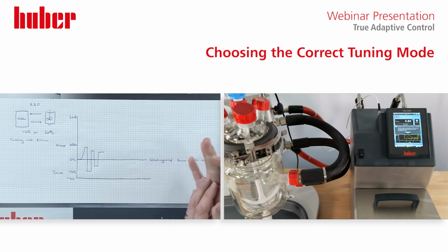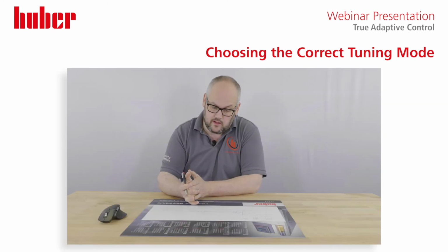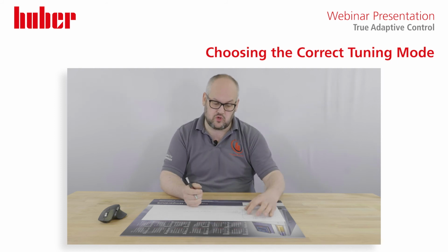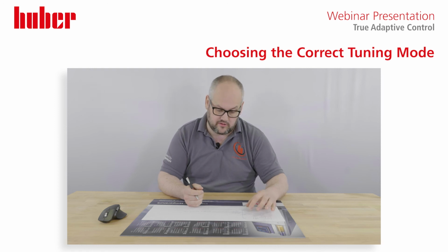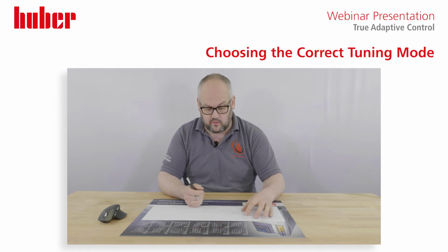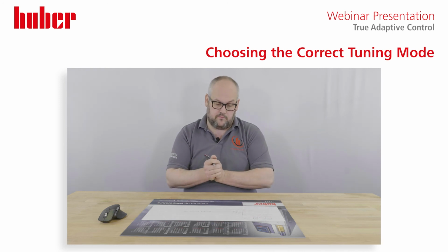Again, you will get a message if the system isn't happy and cannot find optimum conditions. If that does happen, just try throttling back your T-min and T-max, or adjusting them slightly, say minus 20 plus 40, and the unit will scope it out.